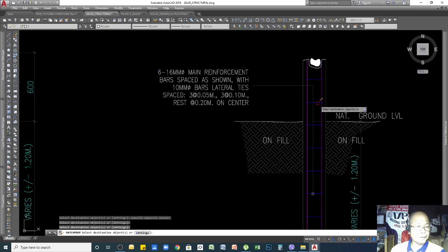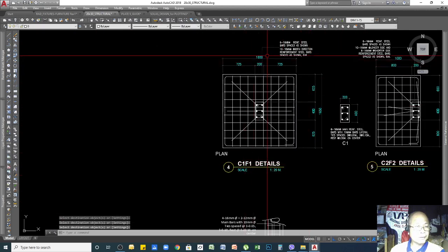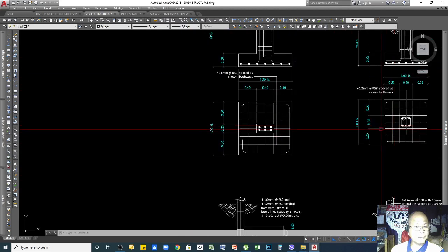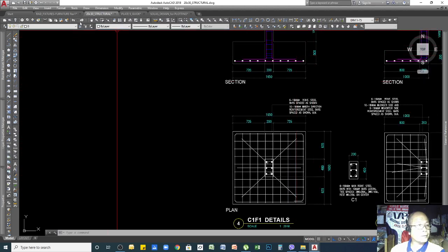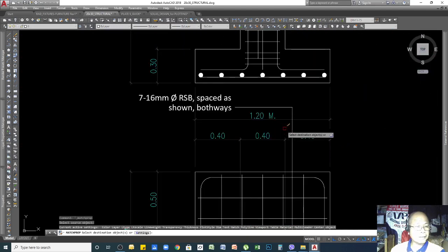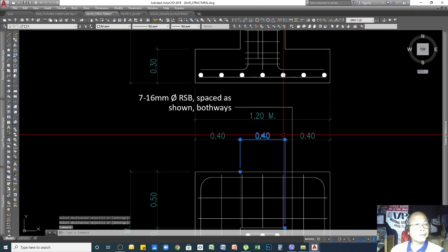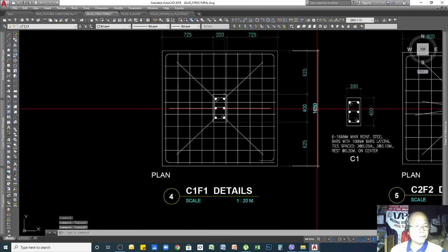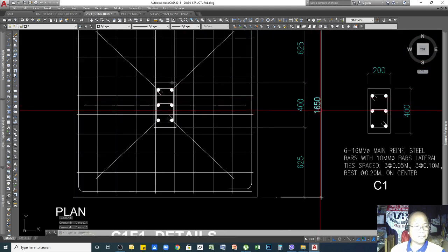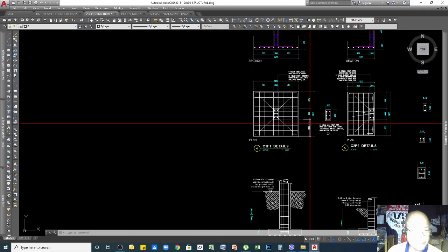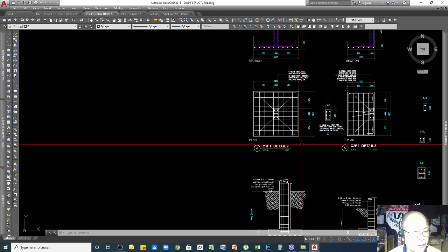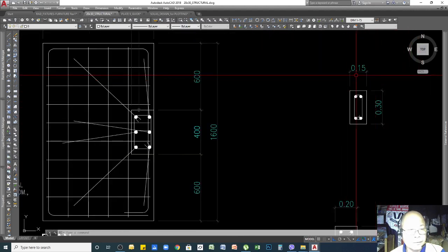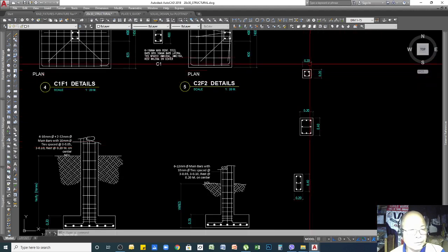Okay, I have here one. This is 165, I already mentioned. This one is 120 by 120. By the way, the units were set up differently, so it's up to you to set up your dimensions. Anyway, 1650 is equivalent to 1.65 in meters. So it doesn't matter as long as the figure is correct. Regardless of the units, it doesn't matter. Okay, like this one, the size of the columns is 0.15 by 0.30. So you can change that also.